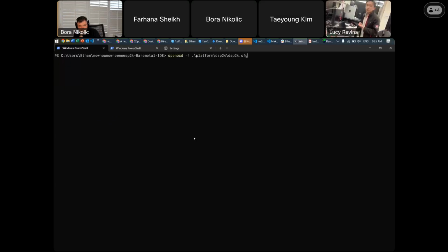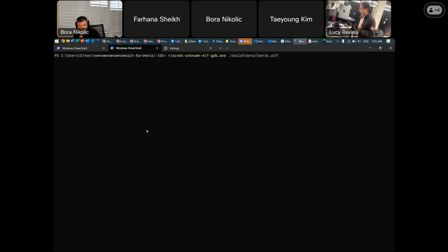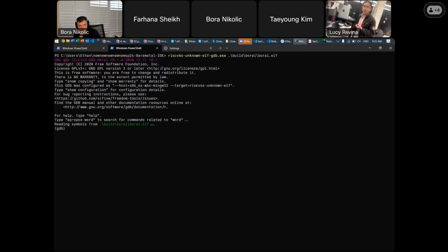For those who don't know, OpenOCD basically abstracts away all the details of the low level commands to talk to every individual chip, which GDB can then connect to in order to give you full debug access like you would expect in the software world. So you have full debug ability to set breakpoints, run different programs, inspect registers, and modify code on the fly, which can be incredibly useful, especially if you're debugging under-verified accelerators and IP, like we sometimes are in the bring up class.